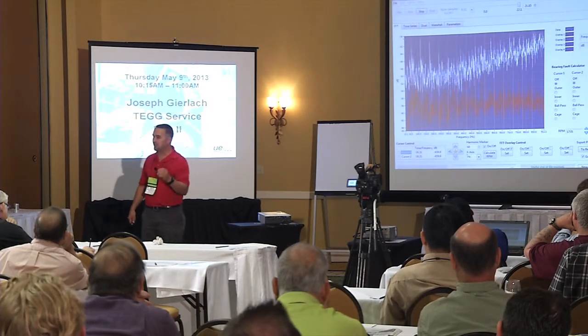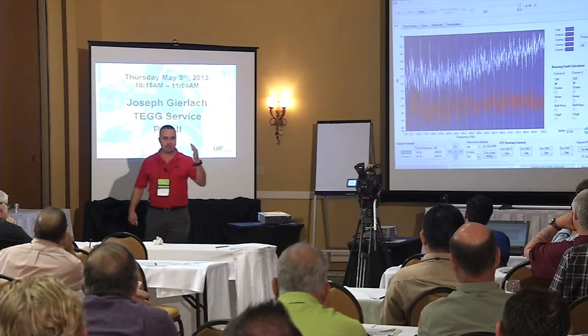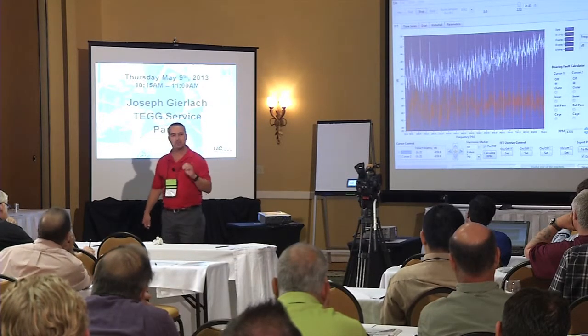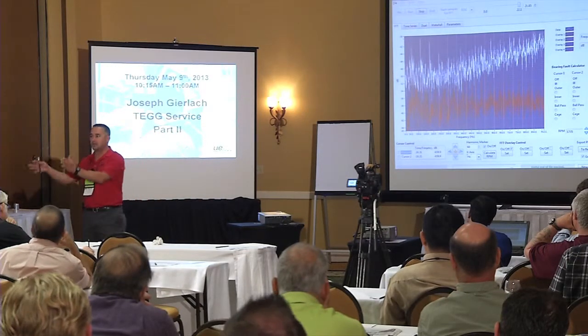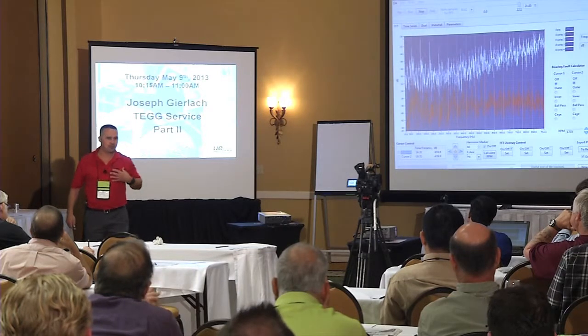But there's a notable difference even on the frequency display, right? So with corona and the 60 cycle hum and vibration, the FFT actually becomes a more important tool to me than the time domain, whereas when I'm dealing with tracking and arcing, the time domain is really more important to me than the FFT.